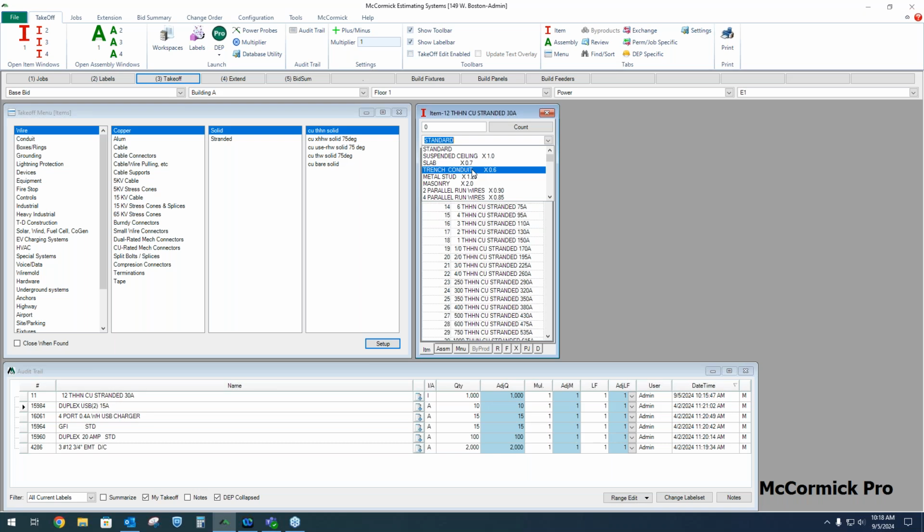These are just a lot of different ways we can look at how we can utilize labor units. It's not always cut and dry, just NECA 1 across the board or NECA 2 across the board. If NECA 1 is my baseline, I might say, well, if we're laying pipe in a trench, or parallel runs, another good example of when we might factor down. We might reduce the time, shave off some time there. It's an easier install. Floors, we factor up. The higher up we go, it takes more time. Different ceiling heights, we factor up for that. So if it's 30 feet in the air, we're installing this run of wire or pipe or whatever,